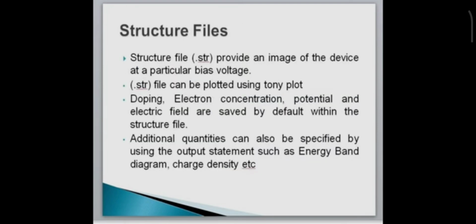The structure file provides an image of the device at a particular bias voltage. This allows you to display any evaluated quantity within the device structure, from doping profile and band parameters to electron concentration and electric field. A .str file can be plotted using Tonyplot.